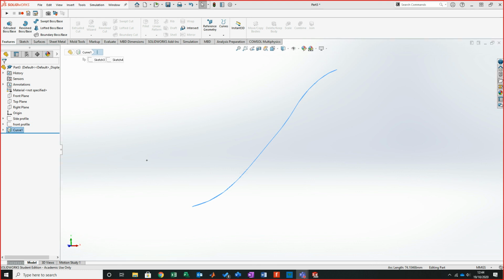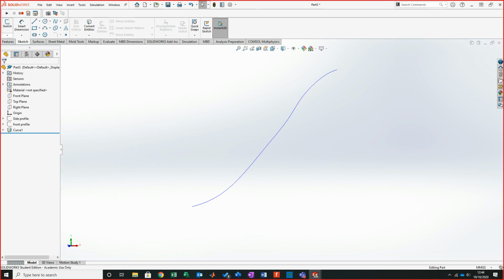The trouble is the way that we were looking at that particular profile then, there were so many curves between it that you probably need a spline with around, I'm just guessing, 3-4 profiles with it. Now, if you were interested in building that up further, what you could easily do is convert that. You could go to a 3D sketch, for example, and you could convert that.